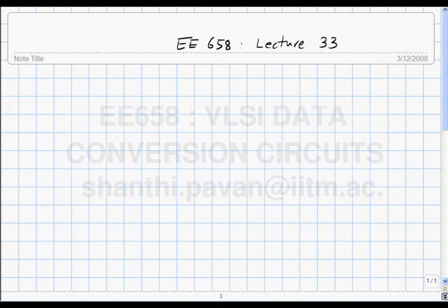On the other hand, in the binary case, the decoding logic is very simple, but the precision demanded of the unit elements that make up the DAC is very large when compared to the thermometer case. And we saw that when we meant precision, we derived the precision needed, which was denoted by this ratio sigma I by I.